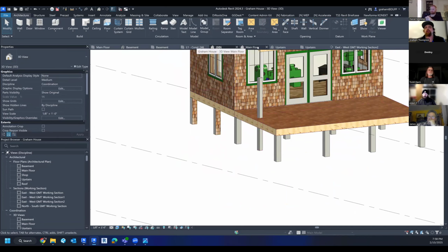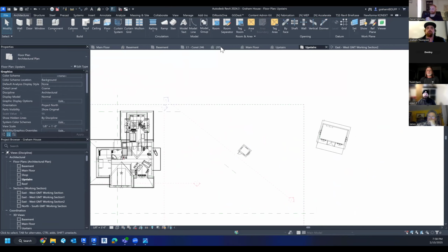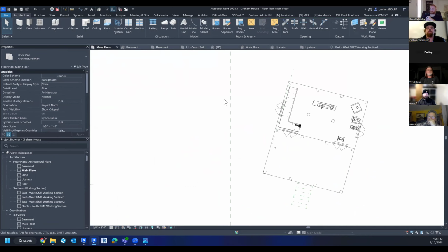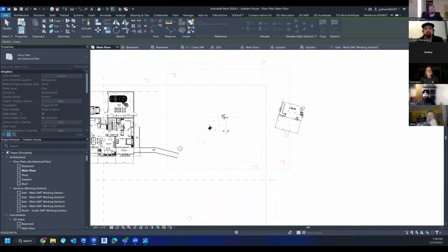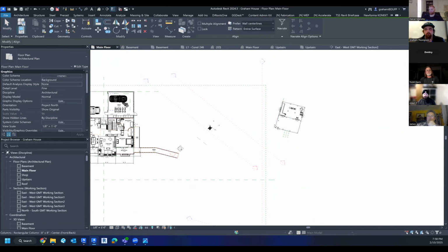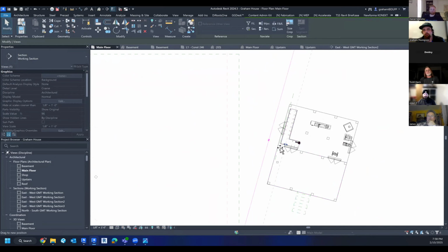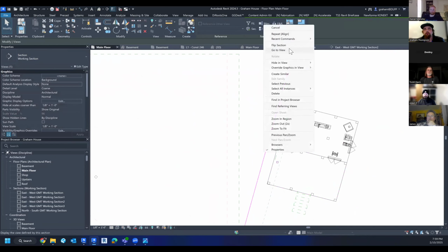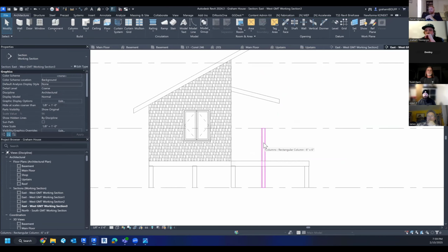If I needed to adjust that height, I could go to, let's go to 4, and bring a section over. And I'll actually make a section that's parallel. I'm going to copy this section and then align it to this wall. And now I can go look at this. And again, here's my depth clipping, so I only want to view this far. And now when I look at this, there's that column I just drew, right?